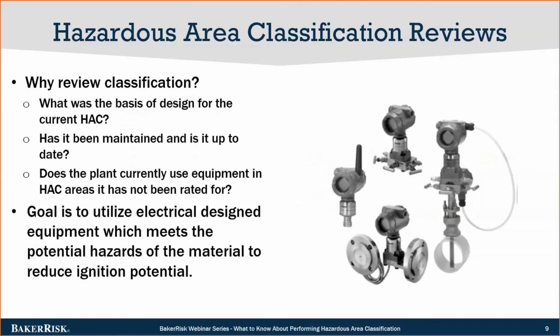As part of the reviews, I'd like to stress that it is important that the hazardous area classification be reviewed. You may ask yourself, well, why review this? I mean, if we have an existing plant and we've had this hazardous area classification or electrical area classification in practice for 30 years, why would we have to change? Well, the answer is there are changes that go around in the process areas.